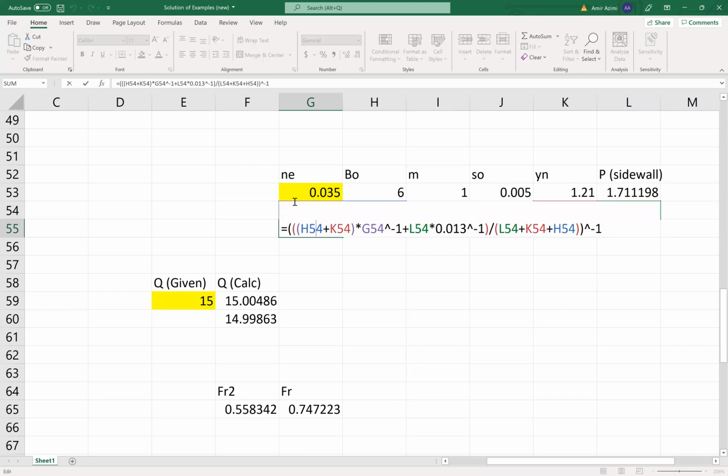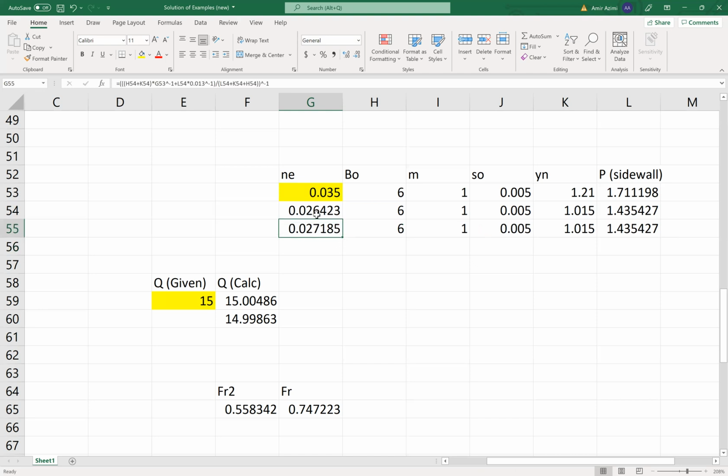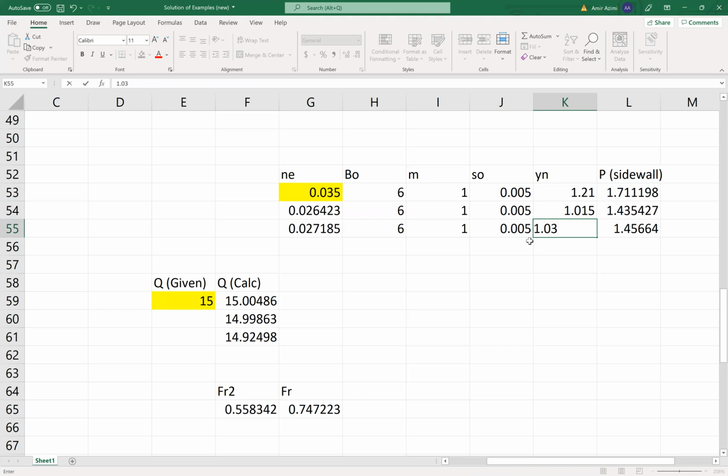So you want to make sure that you calculate the value of the Manning constant for the rock cuts. This is the only change we need to do. And then we have the wetted perimeter, and then I drag this down. So if I put 1.02, maybe more, 1.03, very close, 1.035, 1.033. Yep.